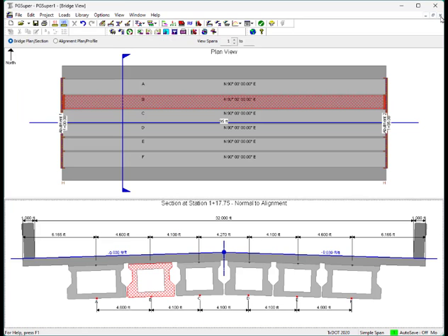There's quite a bit more work to be done here on our bridge to make it a real production bridge. Things like detailing, adding dead loads for loads like shear key loads, and figuring out that live load distribution factors are still needed. But we've run out of time today for this video, and I hope you've learned a lot about how to do girder spacing for adjacent girders.